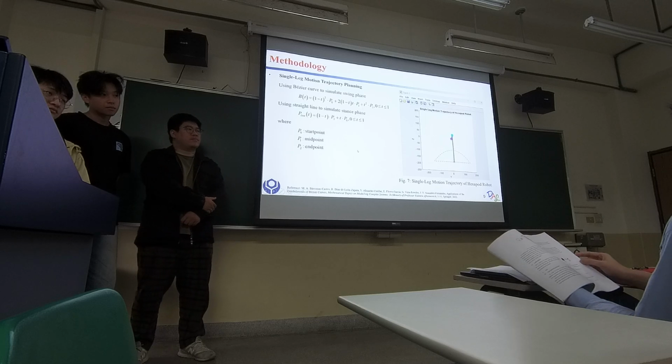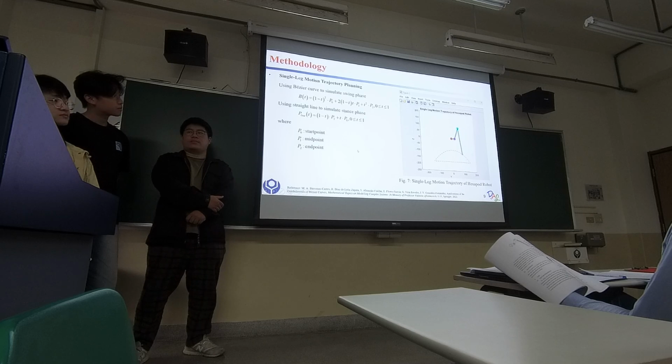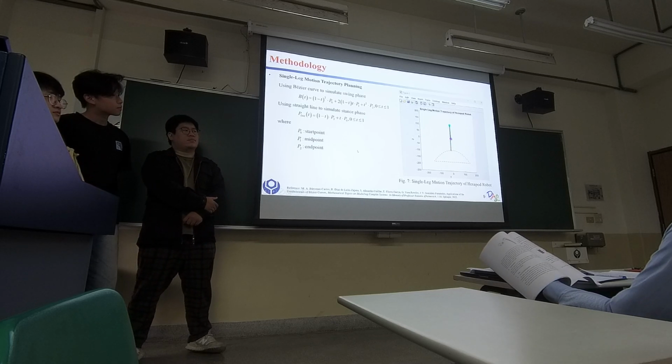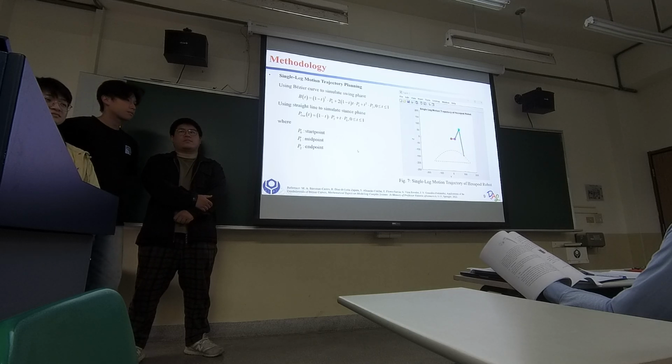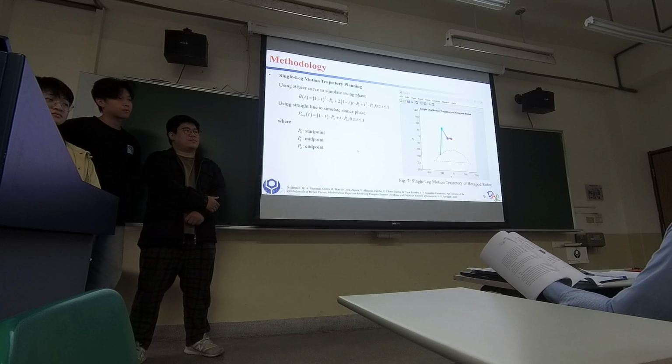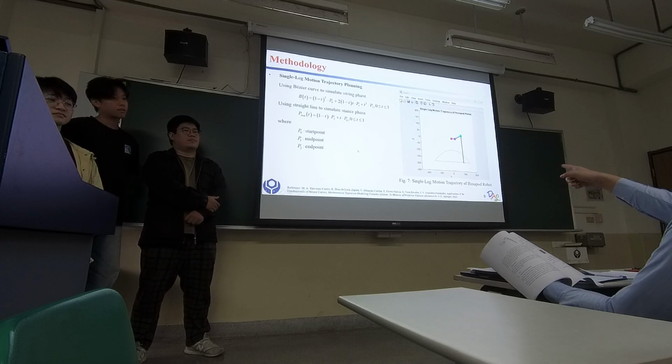Is it forward kinematics? Yes, we calculate a Bezier curve, and the Bezier curve is the trajectory for the end effector. And then you reversely compute the inverse kinematics. Yes, inverse kinematics. I know the theta and put it into forward kinematics. Right, you actually use inverse kinematics. Oh, okay. And then you use forward kinematics to generate the graph?